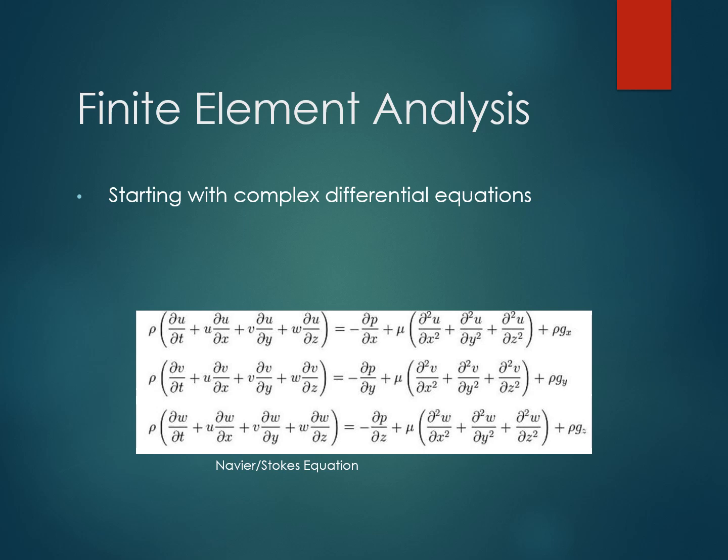So how do we get started with this? As you see here, this is the Navier-Stokes equation, which governs how fluid flows based upon velocities and pressures. You see it's a mixed partial differential equation, where we've got first order terms on the left-hand side, some second order terms on the right-hand side. This is a difficult problem to solve by hand, and so we'll simplify this and then allow the computer to solve it for us millions of times a second.